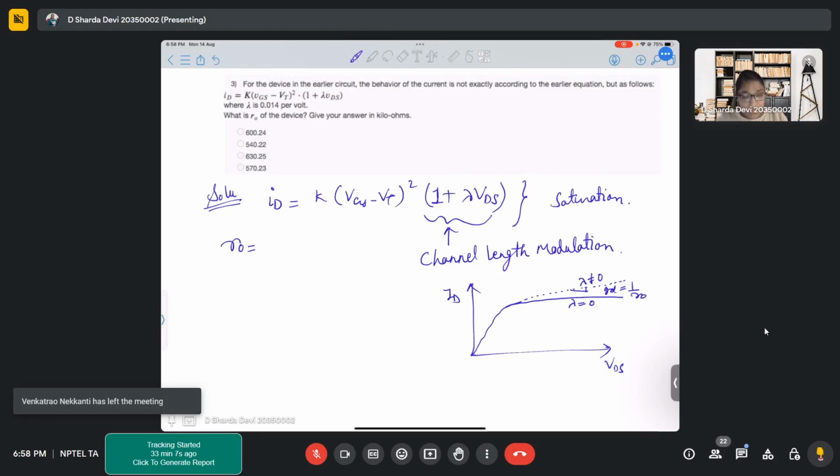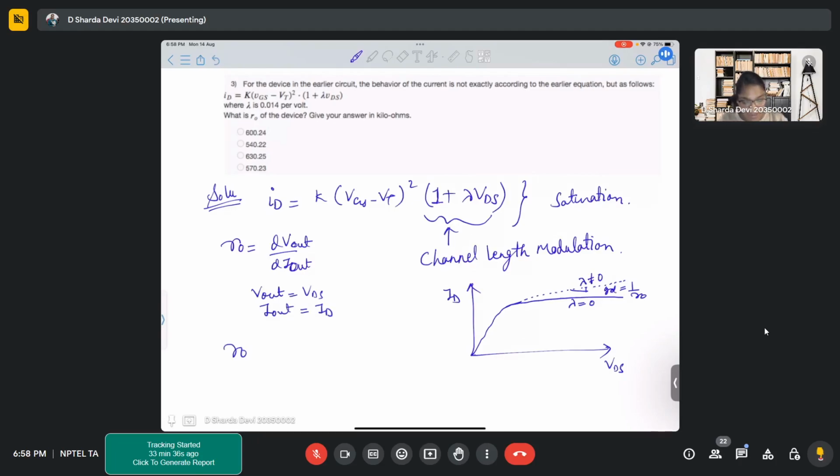Okay, so what is the problem that we have to find R naught? How do we find R naught? It is dV naught by di naught, right? What is dV naught and what is di naught? If I say dV out by di out, here V out is VDS, I out is ID. So when we say R naught, it is dVDS by dID.